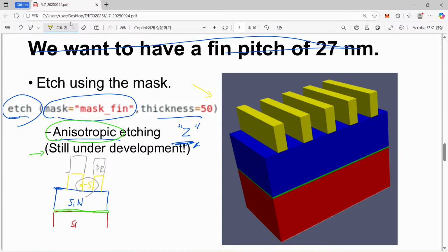I will use this kind of convention many times. Therefore, maybe you can get some misconception that we can pattern any material by drawing certain masking. But please be careful. Whenever we say patterning, that can be done only on our photoresist. It means that this step, introducing the PR layer, exposing, developing and etching, is understood in our consideration.